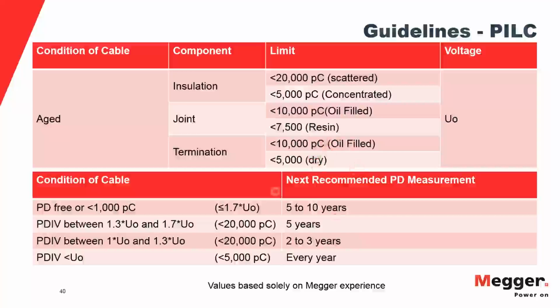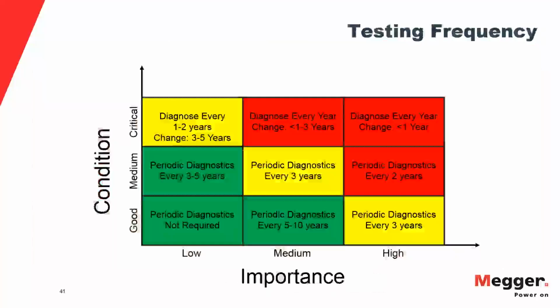Another piece of information that we use for partial discharge is that mapping. So how do we determine this mapping? And that's a process we call localization. In this case, I have one particular partial discharge measured right here, and you can see it's got the arrow pointing at it, and the dot's slightly bigger. And what we can see here is the initial pulse and the reflected pulse, and I have a blue bar down here just to kind of highlight the distance there.